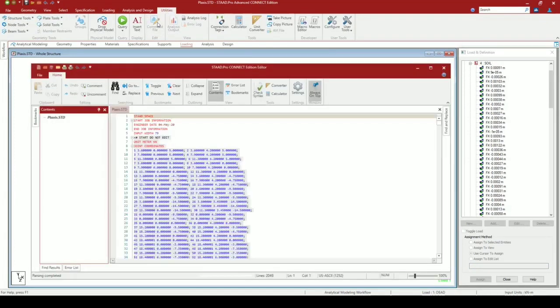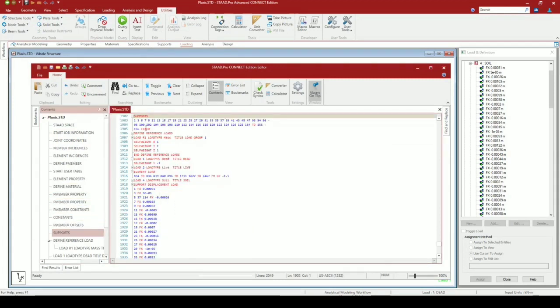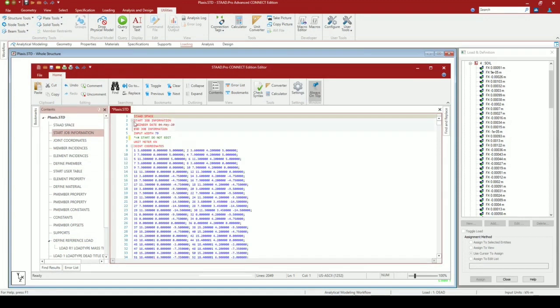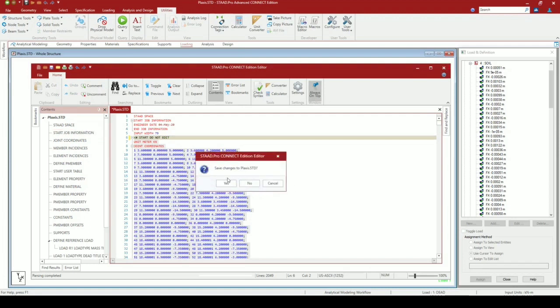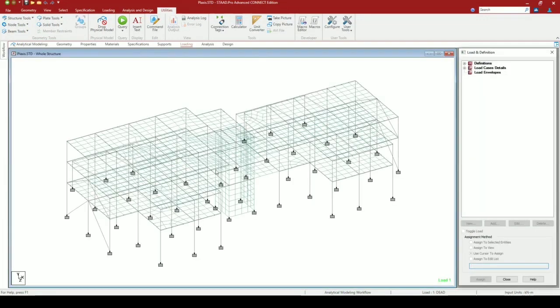Now there is one other modification that we actually need to do at this juncture. STAAD supports two methods for accounting for support displacement, either using a displacement method or a load method. When working with a model with finite elements and plate elements, we need to instruct the program to use a displacement method, which means making one small change from the fixed support to an enforced support. That gives it a different method, as I said, the displacement method, which we can use in this instance.